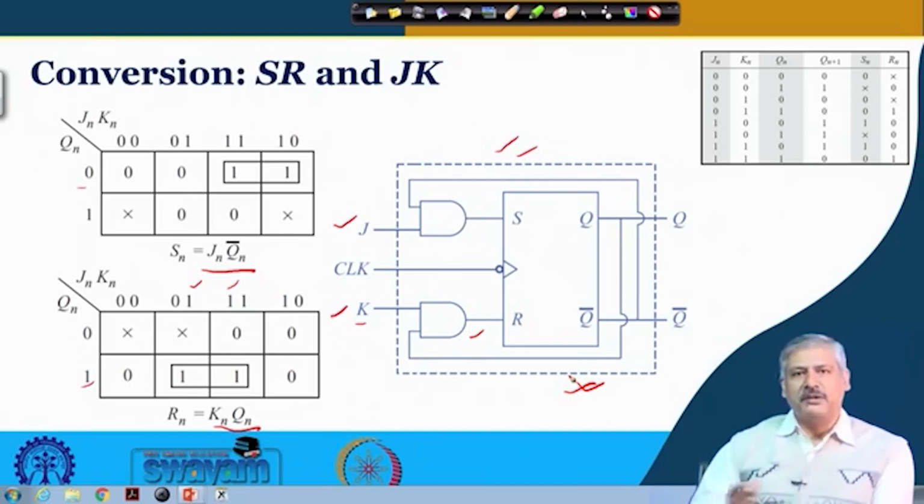Fine. Any flip flop that you require, you cannot directly convert from the characteristic equation or truth table; you go through the synthesis process. First you write the truth table, and then for the changes happening from Qn to Qn plus 1 for a specific input, you write the input that is required for the flip flop being used from the library. Then you use the excitation table with a Karnaugh map or any other minimization process. You get the combinatorial circuit made, and then finally you implement it.